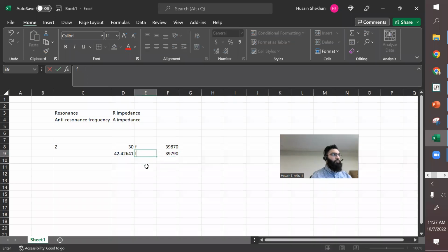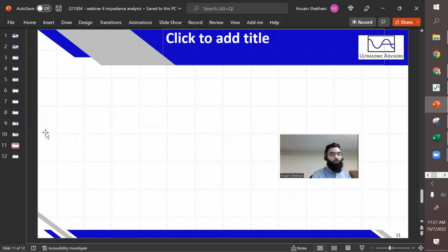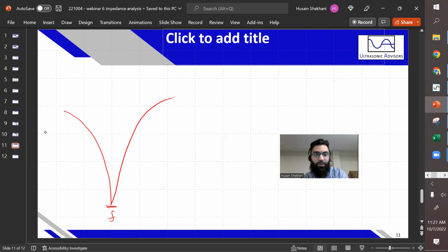That's the other frequency. Basically this is all based on linear theory, like mass-spring-damper formulas. When you have a resonance point, you go from this bottom frequency and find the frequency span that would equal the magnitude you're measuring times the square root of 2, which turns out to be 3 decibels higher.